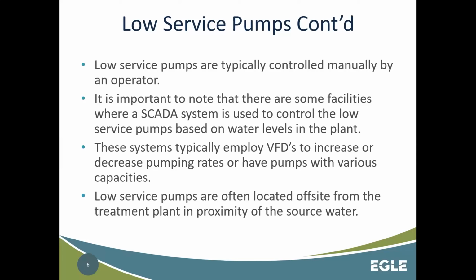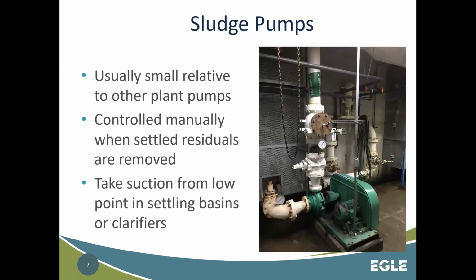Again, these pump systems are employed on VFDs, variable frequency drives, so that we can increase or decrease the pumping rates, right? Or with those pumps that will have various capacities at that low service pump station. Low service pumps are often, definitely, located off-site from the treatment plant, in proximity of the source water. Again, that impoundment, that Great Lake, that surface water intake, that raw water source. So that's our low service pumps.